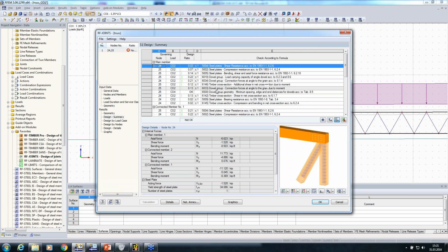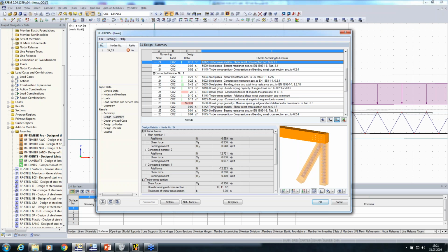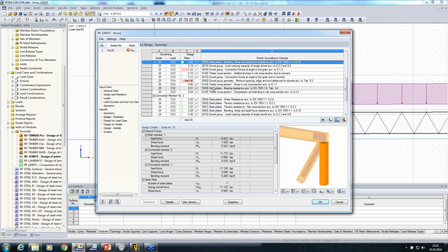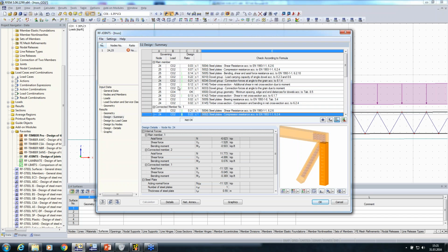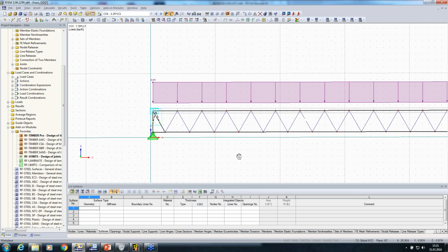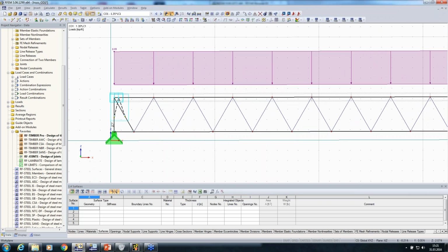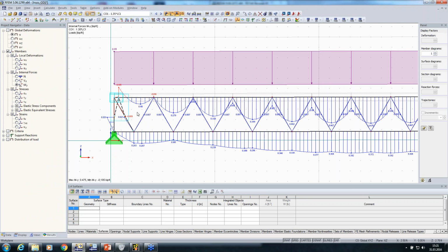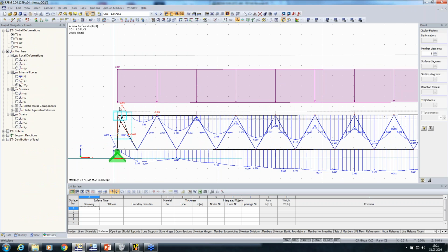So you see, I got some connection problems here, some geometrical restrictions, but the loading of the dowels itself is not so high. That's all okay, but what it did during the calculation is just what I said. It made its own eccentricity, changed it here, and if you look at the inner forces right now, you see, okay, I now have also some negative moment here at the end where it was 0 before, and that's because of the more stiffness I assign with the dowels.